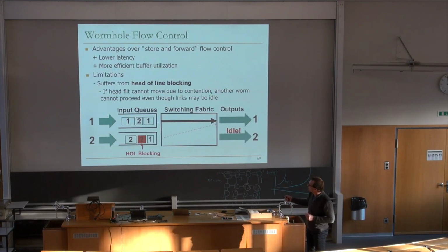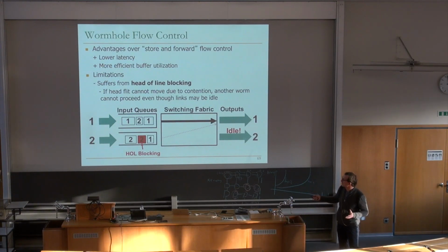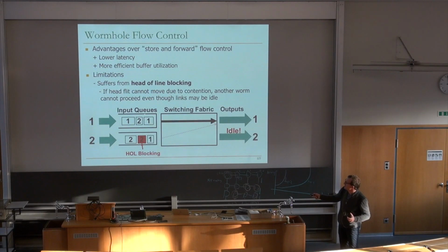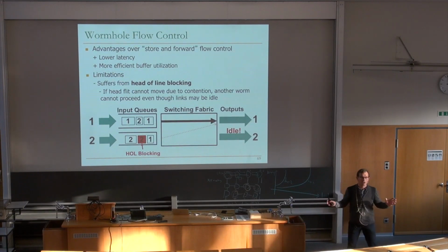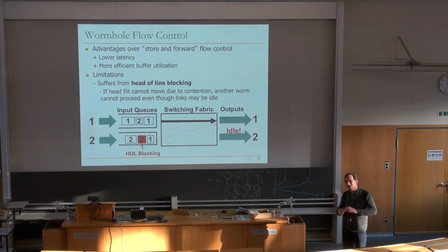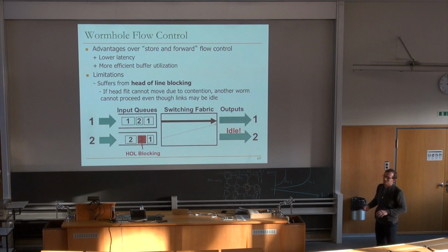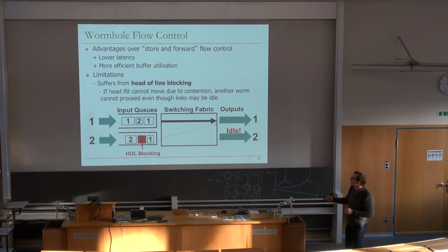Actually, if you were looking at all of the possible flits over here and deciding what to route, this wouldn't happen. Right? Basically, if you were looking at all of them in this input queue, and you're picking one, the head to go to output port 1. Here, you do arbitration also. You say, oh, output port 1 is already allocated, so I'm going to look at output port 2. Is there anyone who needs output port 2? If that's the case, then you can actually send it over here. But that arbitration actually becomes more complex. It's really out of order scheduling. It's a little bit more complex actually than out of order scheduling. And people didn't want to build routers that way. So we're going to solve this problem in some other simpler way.